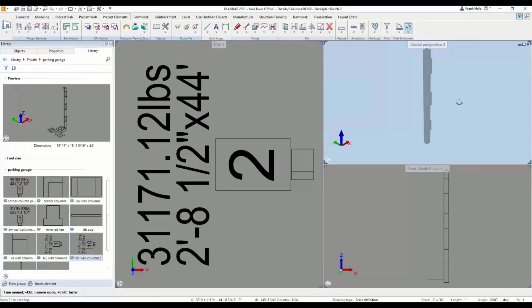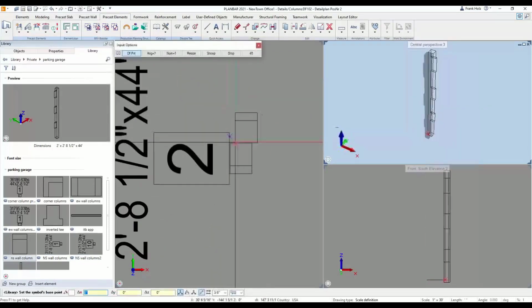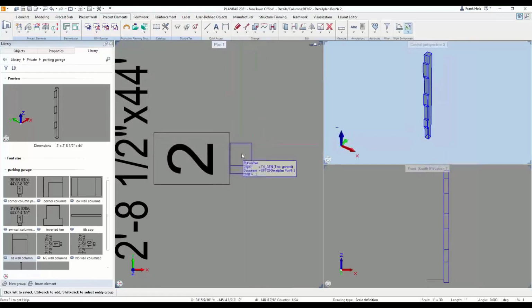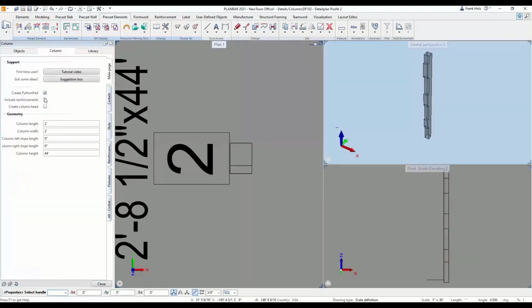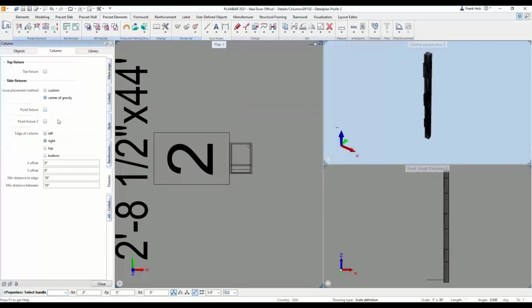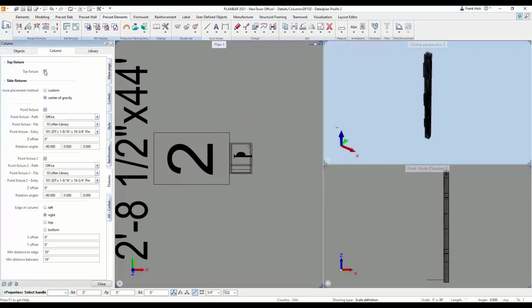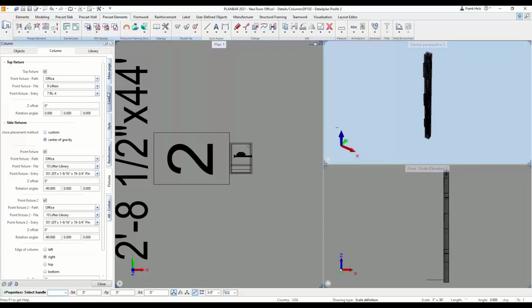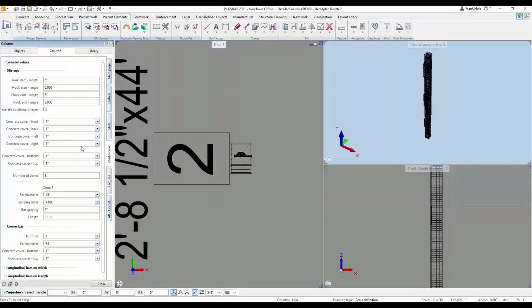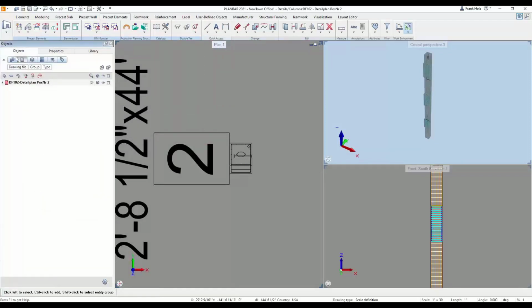This, like I said, is just a simple submodel where we can do all of our self-contained work to a single element and have that work transfer over to the other elements in the model. So again, here, just going to use my app, and I'm going to turn on my reinforcement and turn on some lifting inserts. You can see we can do edge lifters, top lifters, the reinforcement, we can control this in the different zones. We have different styles about how it's all placed inside of here. If I need to change anything, again, it's just parametrically driven, real simple for you to do.